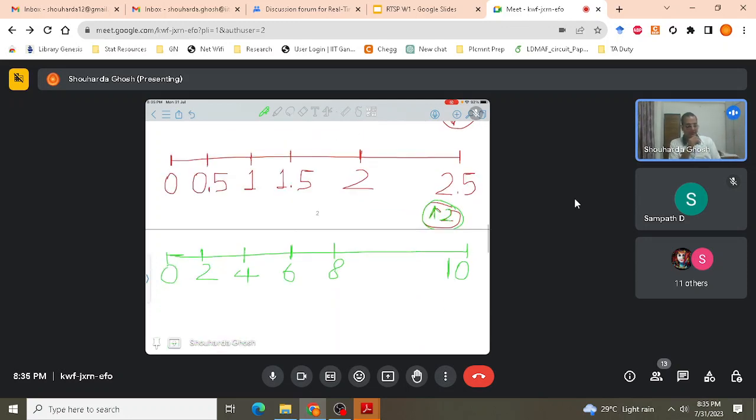Now you see the other case. Over here I have increased my range, okay, 0 to 10 volts. Now I can go and measure even higher voltages that I was not able to measure earlier with my instruments. Okay, maybe I have done something good in my voltmeter, but then you see the issue. You can measure from 0 to 2 directly. You cannot measure the 1 volt that you were measuring earlier. Okay, you are going by steps of 2, 4, 6, so you have increased your range, but at the cost of lower precision. So can you see a trade-off over here?